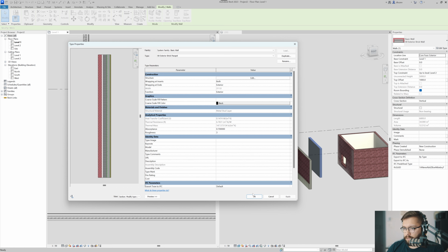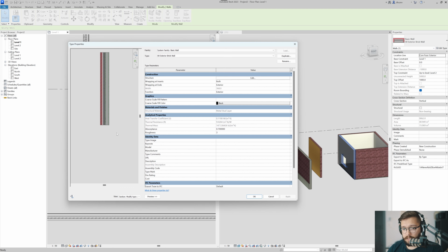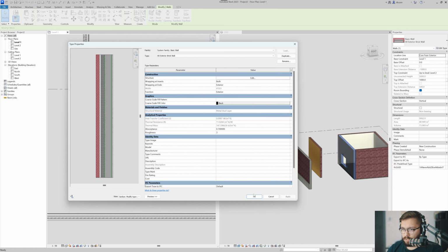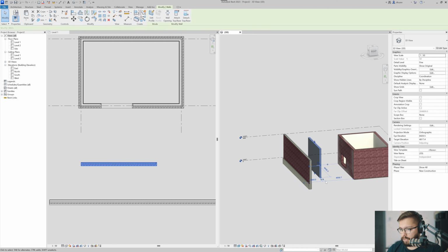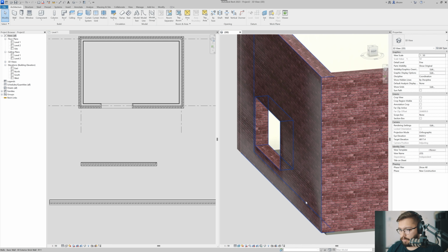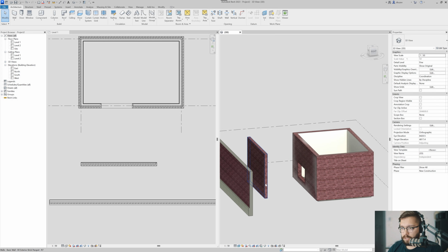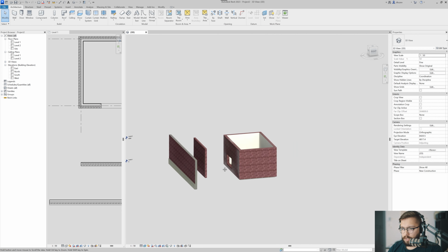And I'll say okay. And for my other wall, I would just want to make sure that I'm back at my typical wall composition instead of 102, 150. So 6-inch metal studs at 400 on center. Voila. So ideally what I will do is take this brick wall and put it on top of this one as a stack wall. Okay, so let's try this.